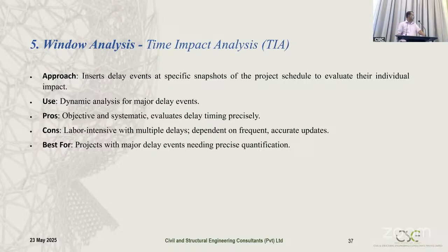And the final one is the window analysis, or time impact analysis. There is a small difference between time impact analysis and window analysis, but commonly both are generally the same. With this method, the approach is to insert delay events at specific snapshots of the project schedule to evaluate their individual impacts. This is dynamic analysis for major delay events.